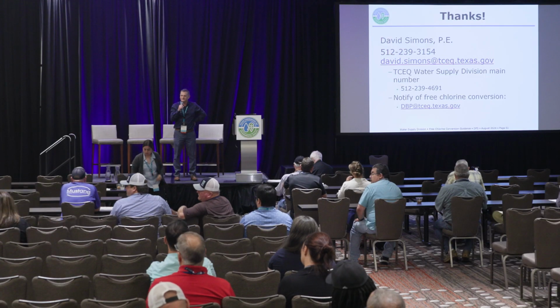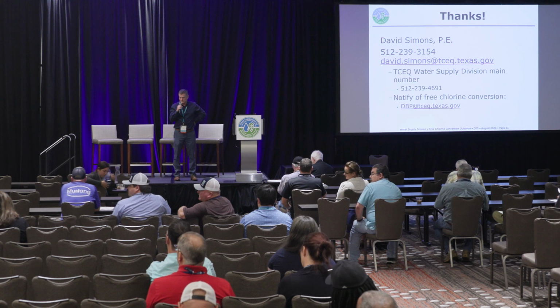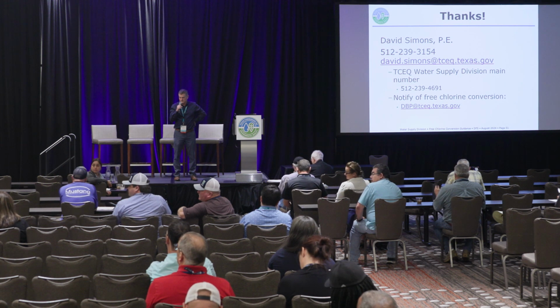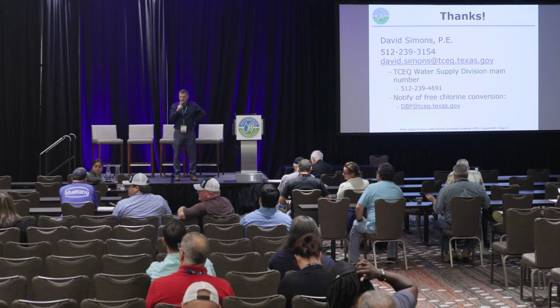On the 2 weeks for the conversion, is there a time frame for us to ask for permission? A month in advance before we do the conversion? If you have your DBP samples coming up really soon, it's better to do it early rather than late. But if your DBPs aren't going to be collected until after the conversion, a week's notice is fine. Even a few days would be fine. It's really when you have that concern of DBP samples being collected in the middle, you don't want to let that happen. Good question.